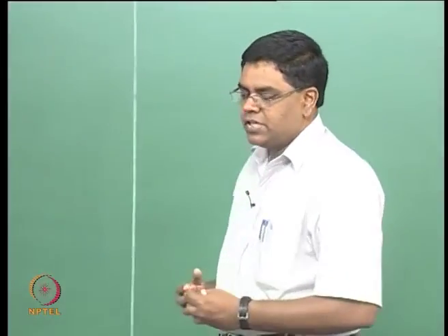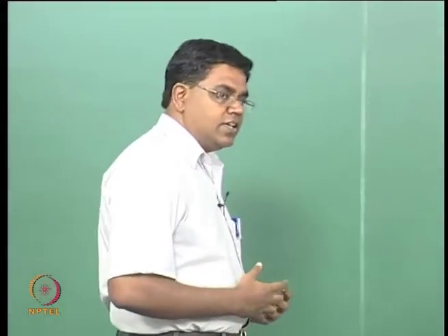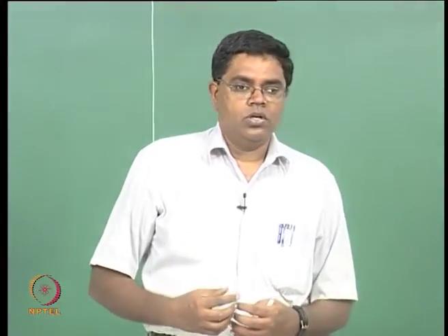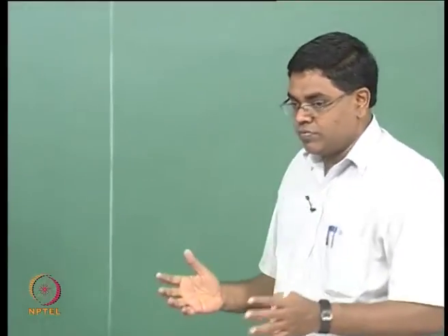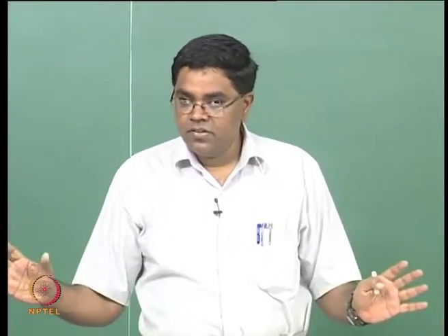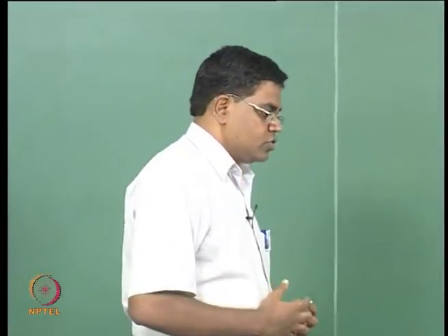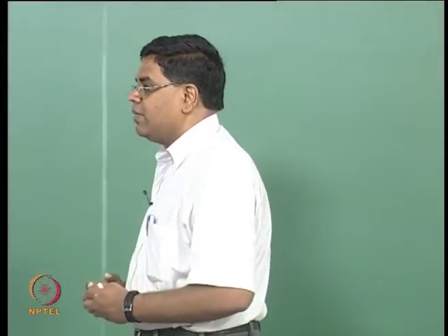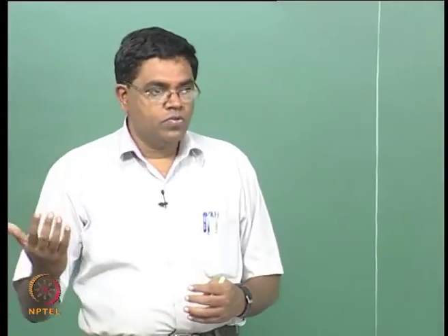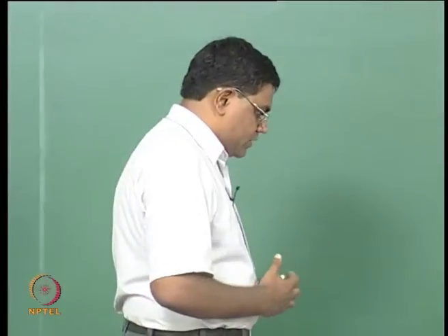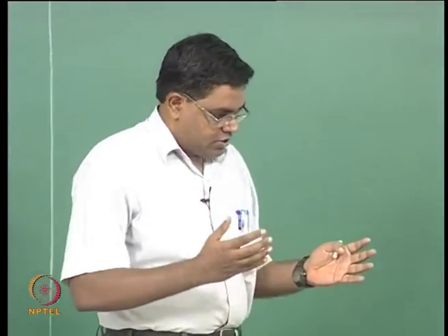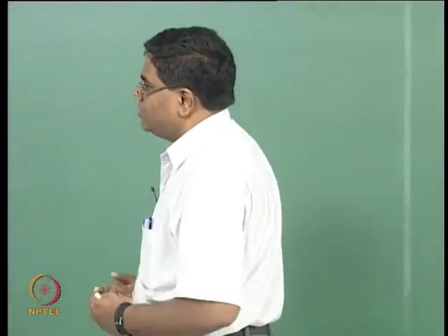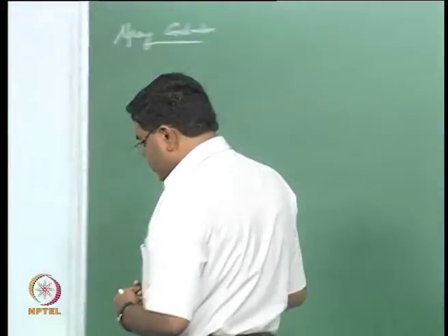So there are lots of different possibilities, and it also depends on whether the spray is dense or dilute. Typically we think about a single droplet combustion mode in a spray. In reality most of the droplet combustion happens only in sprays, right. So spray is the more realistic situation that we need to think about, and the single droplet combustion mode probably happens only in situations where you have dilute sprays. So let us now see if we can take the idea of the single droplet combustion further and see when that happens in a spray. So basically we will now look at spray combustion.